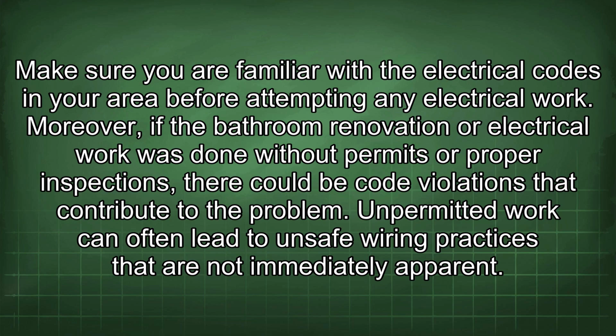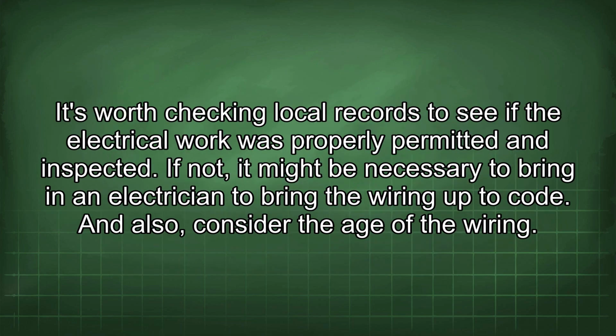Moreover, if the bathroom renovation or electrical work was done without permits or proper inspections, there could be code violations that contribute to the problem. Unpermitted work can often lead to unsafe wiring practices that are not immediately apparent. It's worth checking local records to see if the electrical work was properly permitted and inspected. If not, it might be necessary to bring in an electrician to bring the wiring up to code.